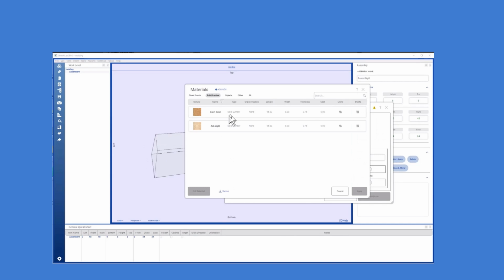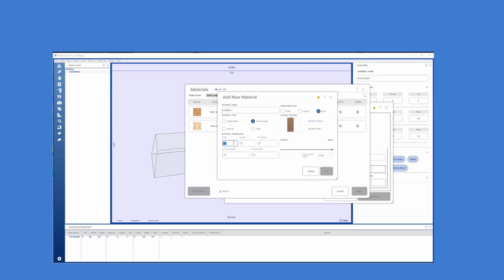You can click the main SketchList menu named Materials. It is at the top of the screen. Or you can click Select Materials on the new board form. Enter the name and the sizes of the material. Be sure to indicate the grain direction of that material. That's important in determining the surface and the edge. Having the correct size material for the board is critical.